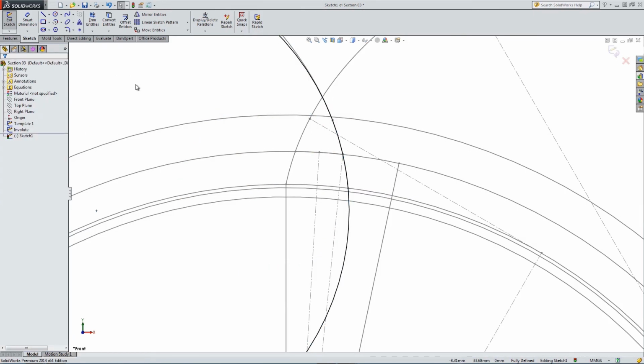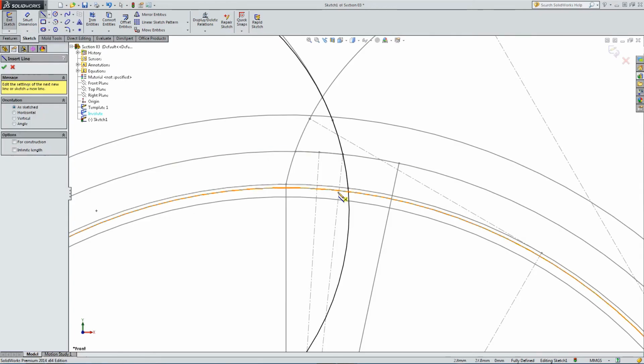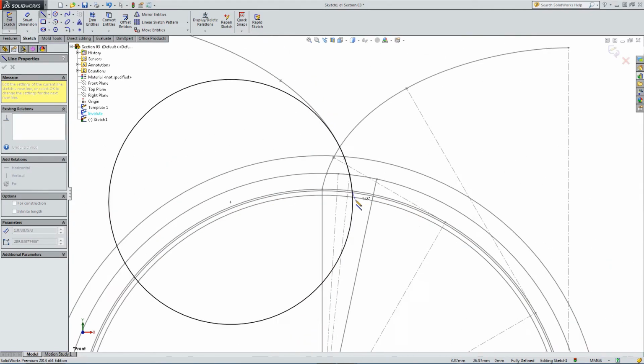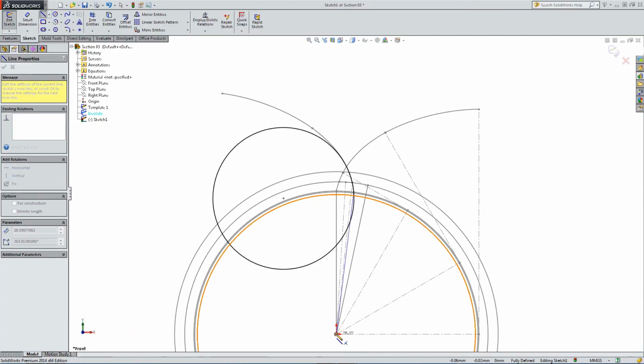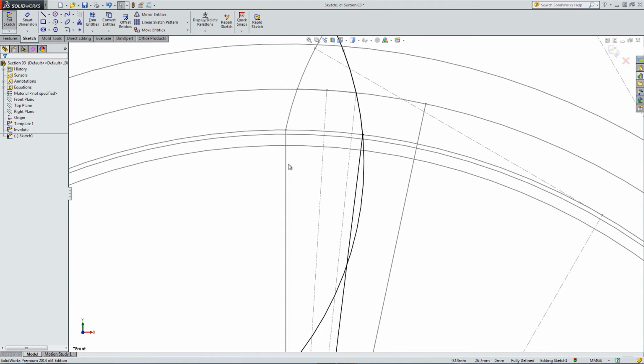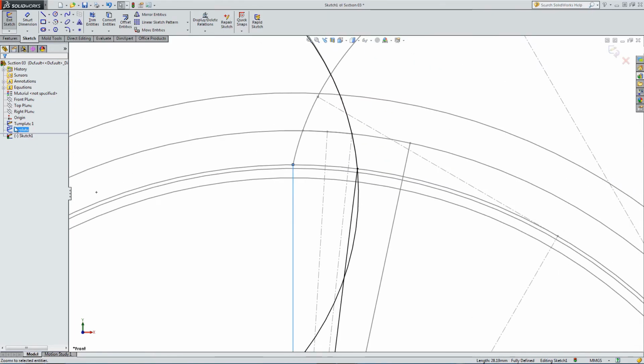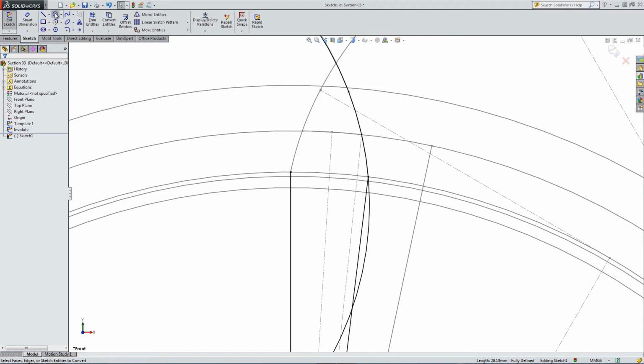This is because when I was working out how to make this video, this is where it generally went wrong in the practice sessions. So using a formed curve, as opposed to a spline, just stops those error messages from creeping in.